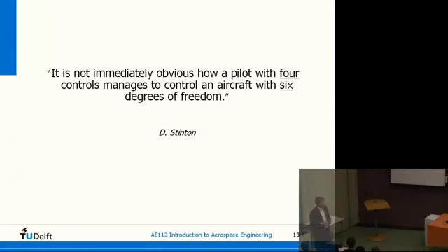Slipping is if you fly the aircraft relative to the airflow with the angle to the side, horizontally. So then you have more drag. It's often done by gliders, for instance, during the approach. If they want to brake, you often see them just pushing the rudder and the aircraft sort of drifting, like with cars. You call it drifting, right? But it is indeed, you create a slip angle, and then you have airflow from the side, creating a lot of drag. Drifting itself, in aircraft, refers to when the airplane moves different from its heading relative to the ground, so caused by the wind, for instance.